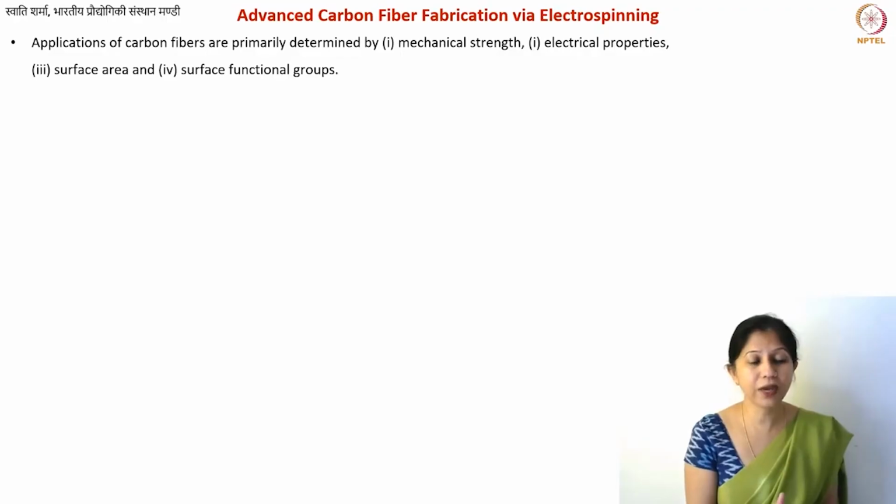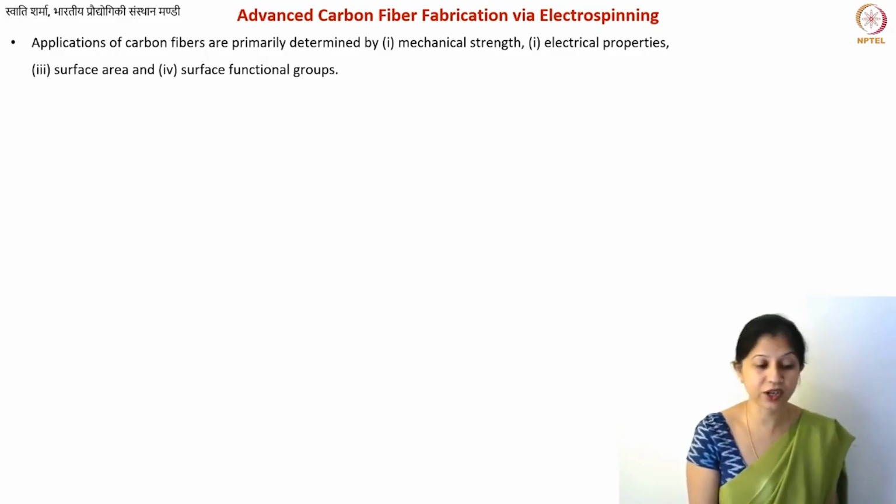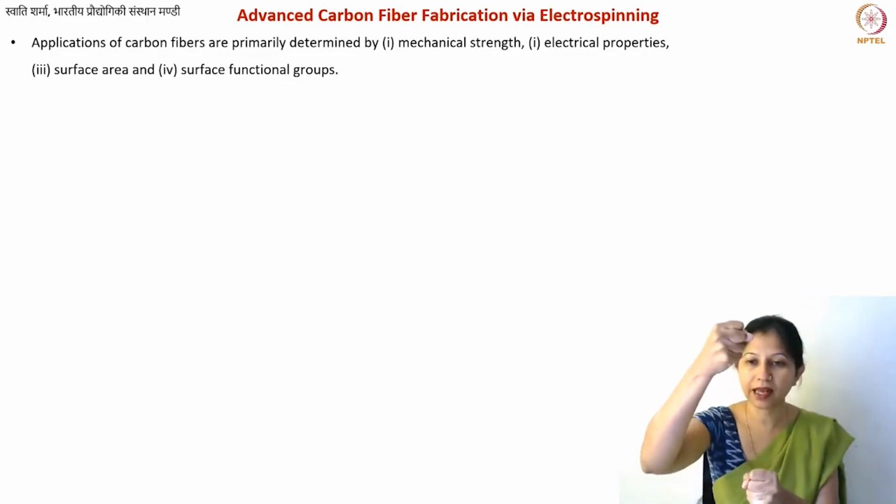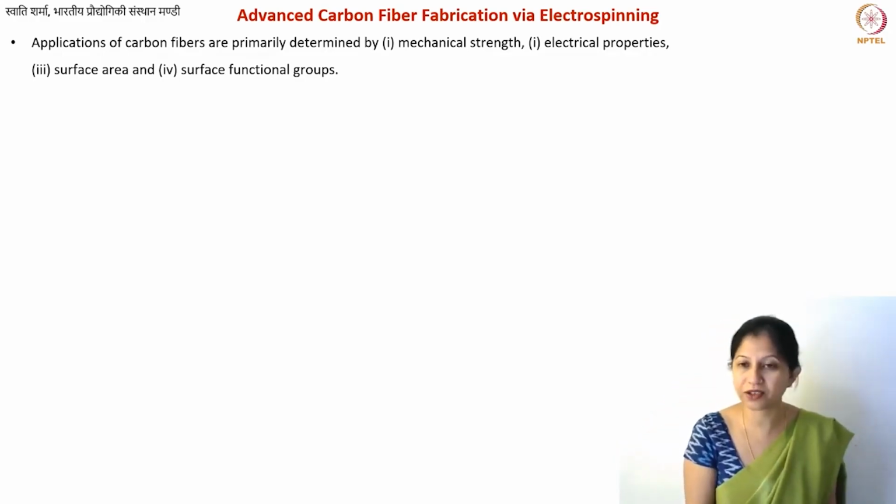First of all, we test the mechanical strength of our carbon fibers. For manufacturing applications, you will typically not test the mechanical strength of individual fibers, because you're almost always using them as bundles or ropes. So for these threads, ropes or bundles, whatever you call them, whatever the required diameter of our bundle is, we take that bundle and test its tensile strength. Compressive strength also becomes important, but primarily tensile strength.